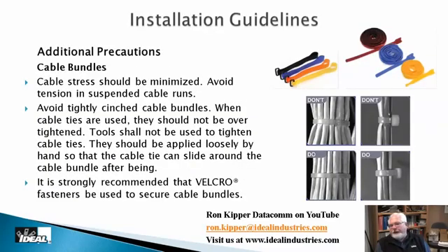When you're bundling cable together, what do you use to bundle it together with? There's a lot of different devices out there today. You'll find everything from basically cable ties to Velcro cable ties, and there's some actually very cool wire management devices they use today to help straighten out that bundle and make it look nice and neat. Over the years, we've learned not to pinch the cables with the cable ties and deform the shape of them. That's not good. We want the tie to be snug, but not damaging the cables.